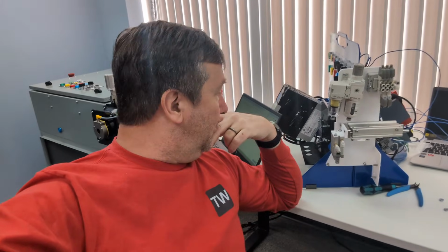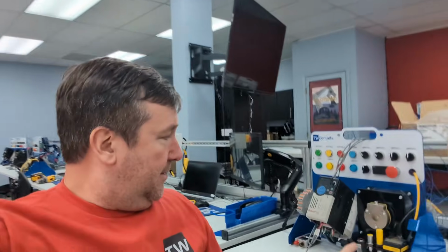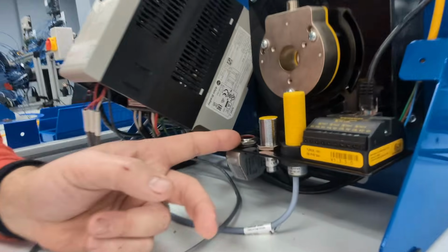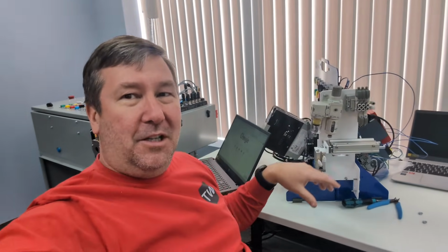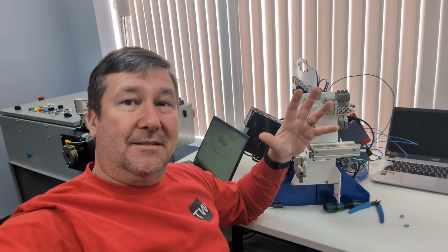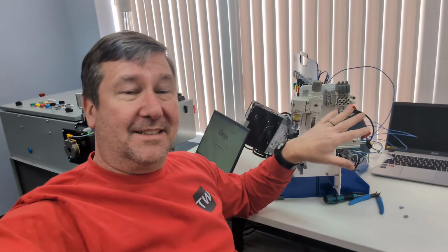A sensor that can view something like, well, we have the laser sensors. Actually, that probably is it. We probably just need to rearrange. You know, this probably that laser sensor, probably shooting down, and you could say once you're to a certain height, turn that solenoid off. But so the whole point is to make a really basic pick and place. One, so you can learn about a pick and place, but also so you can learn the basics of pneumatics.